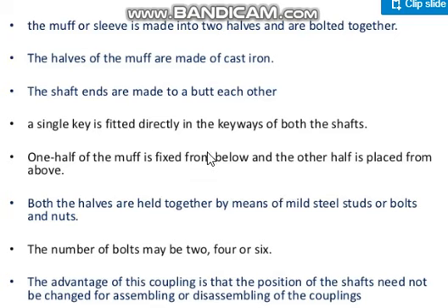I told you the advantage of split muff coupling. To make the joint, to make the assembly, there need not be any gap between those two shafts. Sometimes shafts will be very heavy and big. If it is a muff coupling, you need space to insert the muff coupling, whereas in case of split muff coupling, you need not have any space.